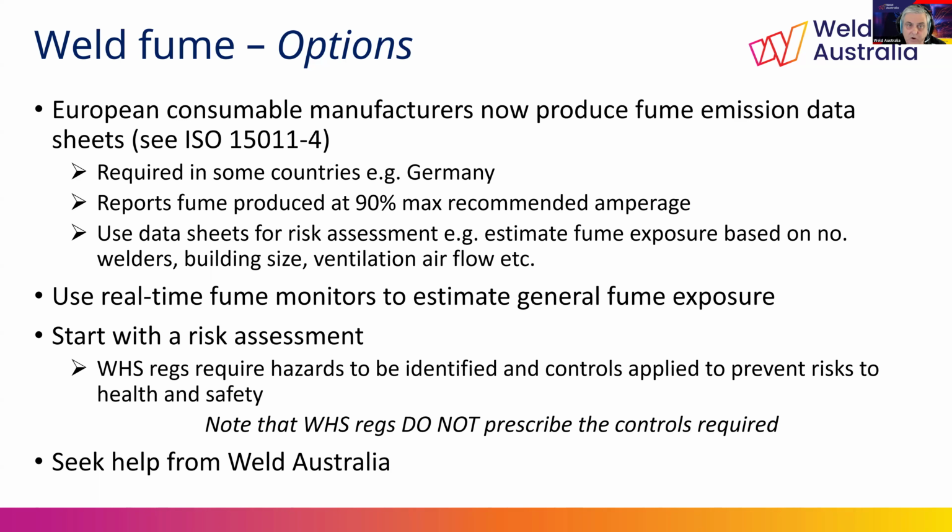Now, separate to this, real-time fume monitors are now available, and I have spoken about these in past webinars. They are particularly useful for estimating the fume exposure for people working near welding operations, but they are not a substitute for formal air monitoring by a hygienist.